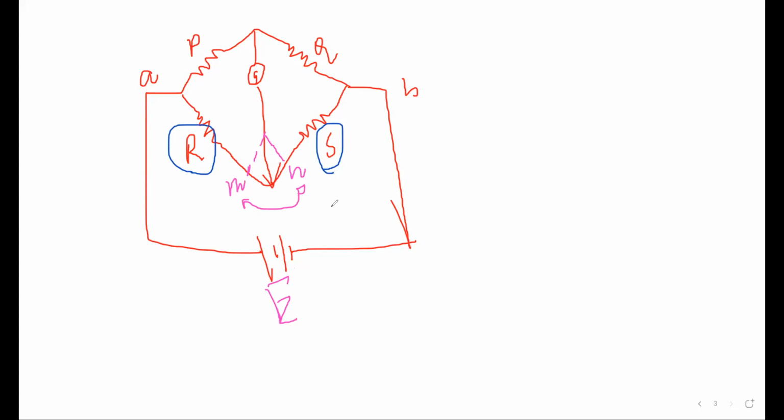So by connecting the galvanometer from M to N, we choose another intermediate point D in the Kelvin bridge. That point D will be this one. D is the intermediate middle point. If the galvanometer deflects to M, then it is showing less resistance. If it is N, then it is showing high resistance. And the intermediate point here is small d.